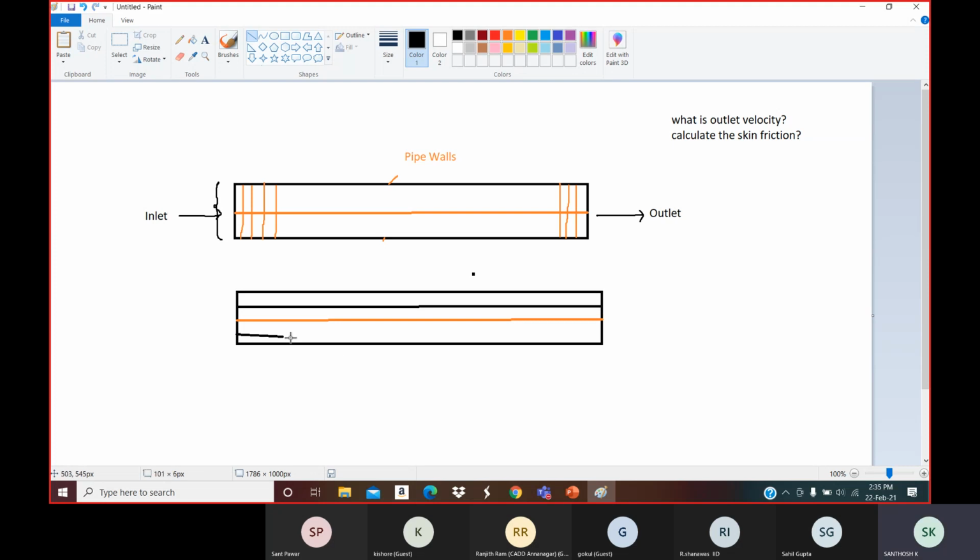The rest, in the middle portion, I'll go with the default mesh. So very fine splitting will be generated in this area, and it should be connected with each and every element. That is the basic logic before we start off the problem.